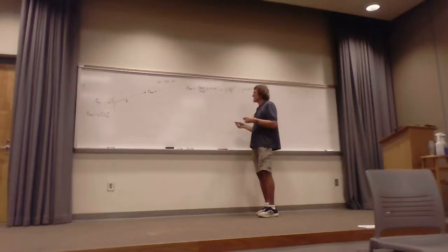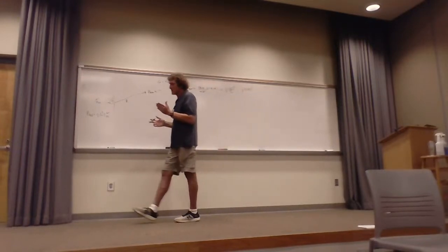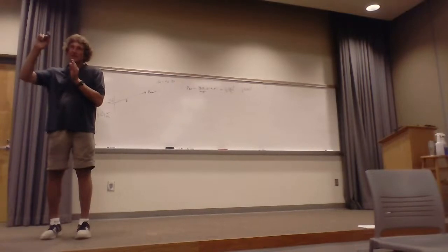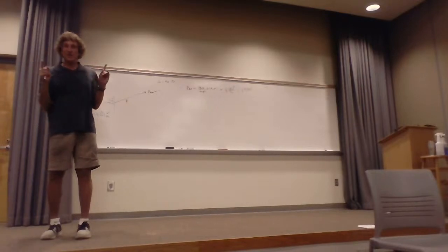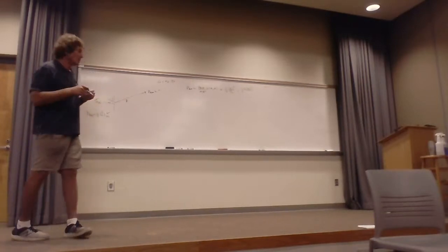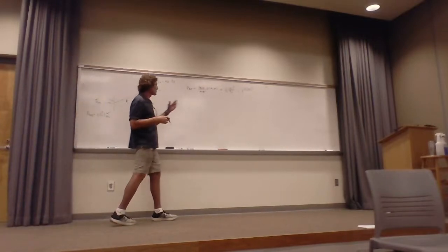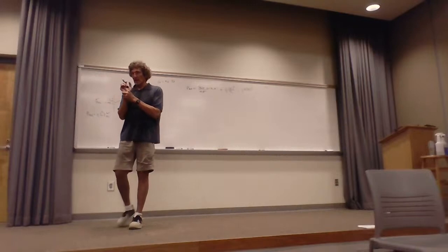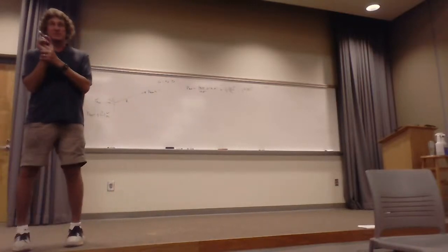Now, by the same token, if you have the gain as a function of angle, you can plot gain versus any angle, theta or phi, and you can see where it goes down by 50% of its maximum value. You can easily get the beamwidth, right? I don't want to spend much time on that. I'm just trying to tell you you can. Ultimately, when we critique an antenna, we want to know the gain, the general formula for gain. We do antenna measurements, and we get mathematical statements that approximate that. And then we need the radiation resistance.